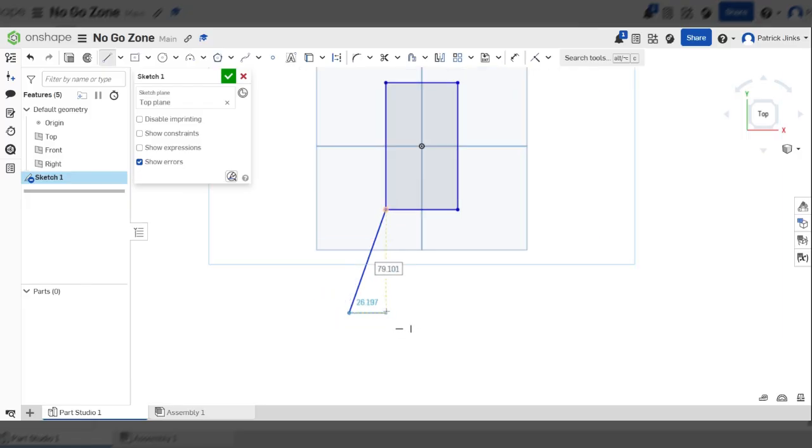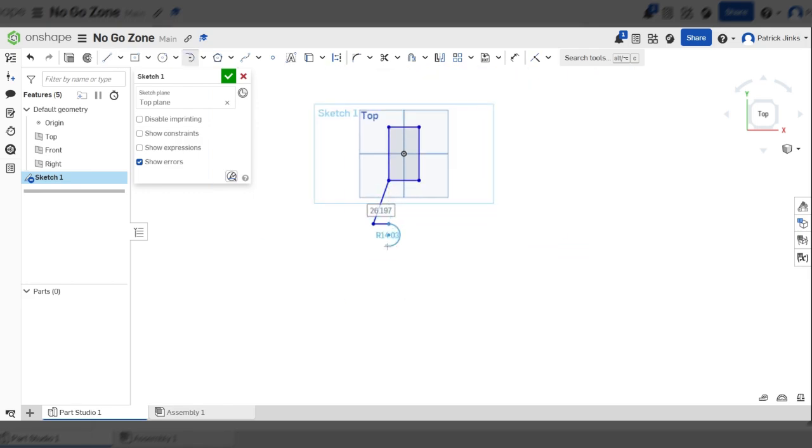From the bottom of the rectangle, I'm going to draw diagonally out. And then I'm going to come back in and it's going to make one of the wings or the side pods. And you can see there, I'm automatically snapped to my original line, my original extension, which is what I want. So I can see that yellow dotted line, I'm snapped to it. I'm going to click there. I'm just going to move straight down again and move it 90 degrees into the middle there. Okay, and then press escape.